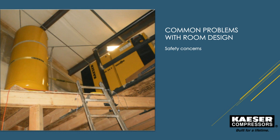Obviously, my concern here is that this 25 horsepower compressor with the integral dryer weighs about 15,000 pounds. So you want to make sure that if you're going to build a mezzanine, it can hold the weight of this equipment. Further, if something goes wrong with the no-loss air drain, the storage receiver can fill up with water, and now you have a significantly increased load on that mezzanine as well.